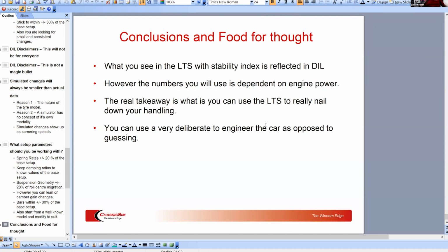Once you've whittled down, you go to the track, sort through the data, and do your business on track as is. Now, if you've got really good computing resources and a dedicated performance engineer, yes, they can use simulation if you need to ask some very quick questions. For example, I had an IndyCar customer whose performance engineer would be feeding stuff from ChassisSim to the race engineer in real time. But typically, you're focusing on the race engineering of the car, looking at the data and correlating it against what you're doing. Once the session is done, you look through the data and debrief with the driver. That's when you crank out the simulator to figure out, is there anything that we missed here? Is there anything that's not adding up? That's when the simulator comes back at the track.